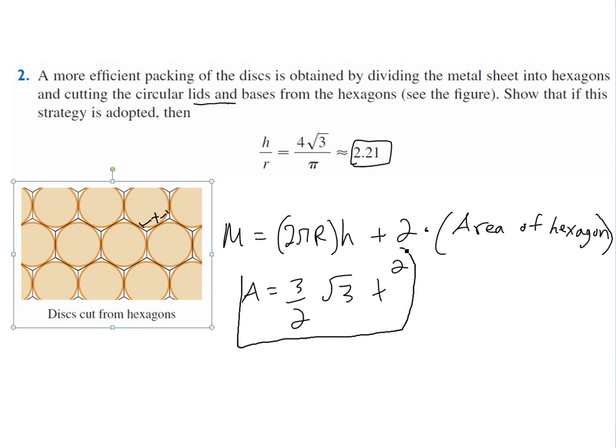You could click on the Dropbox link below to see this, but we want this in terms of r here. As you see, the inside circle, this length here in terms of t, just equals... Again, you can see my video in the Dropbox link below on hexagon properties and the area. I showed that the inner radius of this hexagon, the r, is just going to be equal to square root 3 over 2 times t.